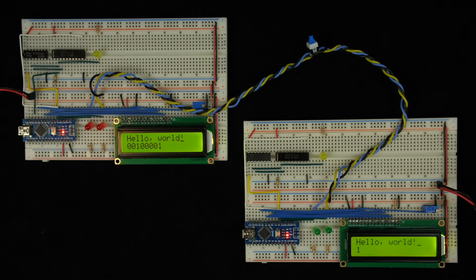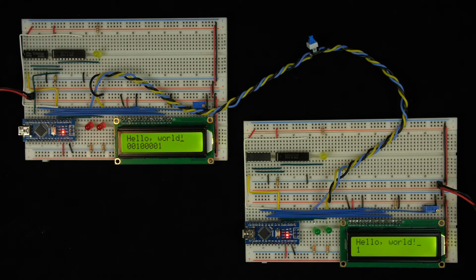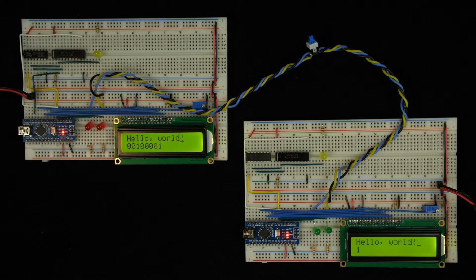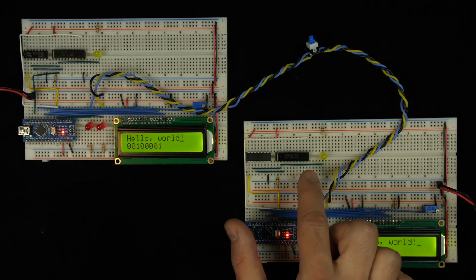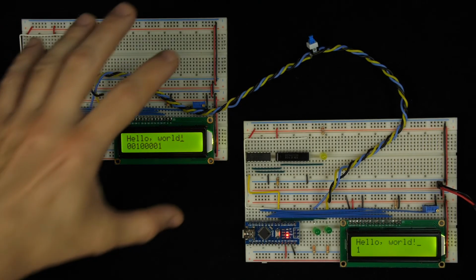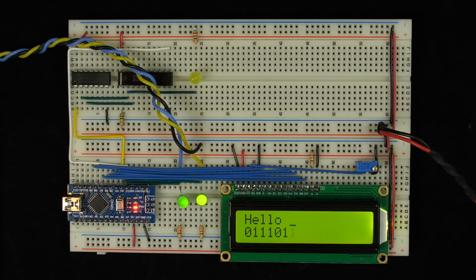But actually, if you think about it, this leads to an interesting property. Anytime our message has an odd number of 1s, we'll tack on a parity bit that gets us to an even number of 1s. And anytime our message has an even number of 1s, well, then the parity bit will be a 0, so we'll still send an even number of 1s. So in other words, no matter what message we send, the transmitter is always going to transmit an even number of 1s when you count in the parity bit. And there's actually a name for that, and that's called even parity. And so we can actually describe our transmitter now as having this property of transmitting even parity. So that's actually really convenient.